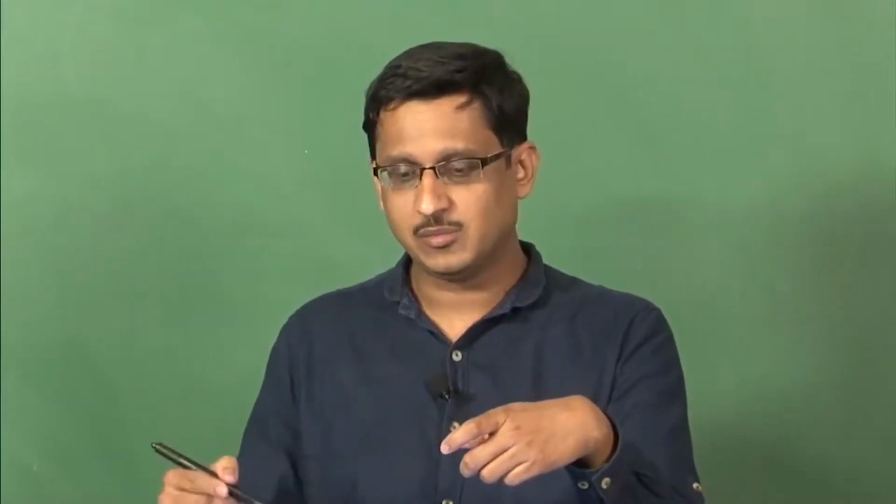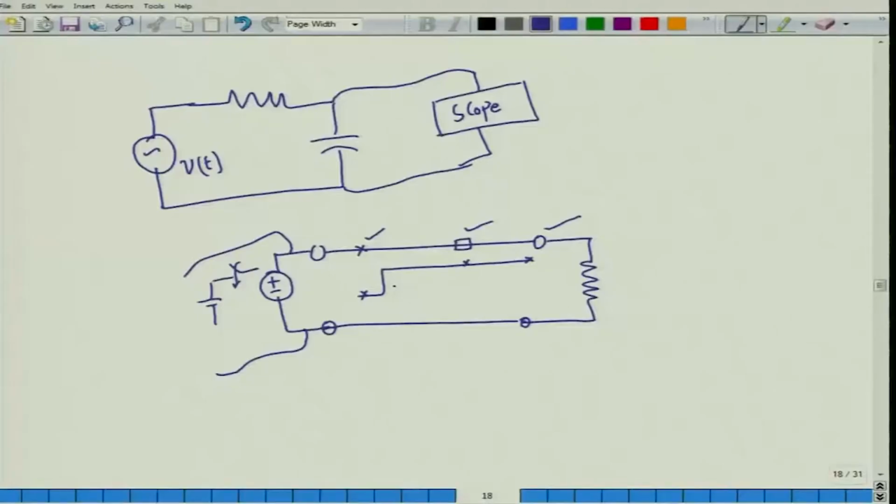So the quantity that I am looking at is varying with respect to the position on the transmission line, and since any position can be represented by a vector, what we actually have is some quantity which is varying in terms of the position vector. So at different position vectors you have a different value for this particular quantity, and the quantity that we were considering was the voltage. So what we had considered was a quantity that was varying with respect to Z when the time was considered to be some constant time t equal to t naught.